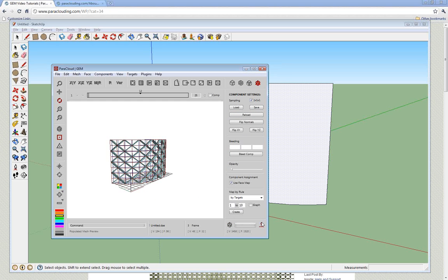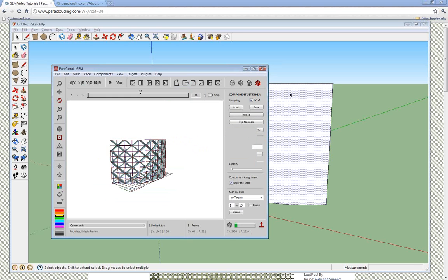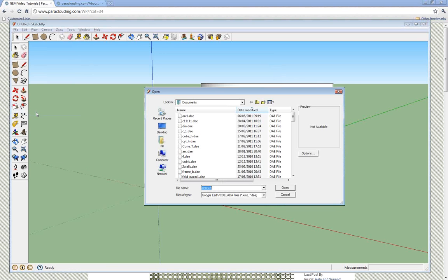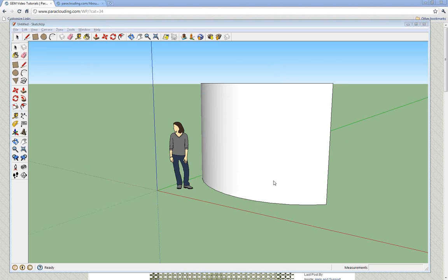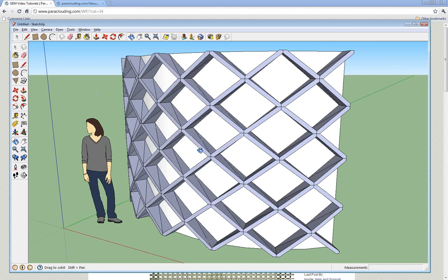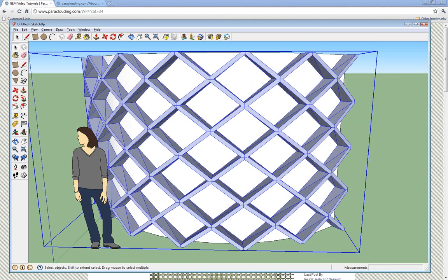And I will export that, using Collada output as well, which will allow me to then bring it into SketchUp by importing that Collada output. So you can see that I could get the geometry to read and write, and simply take this, and of course I can even clean it up a little bit using the smoothing option.